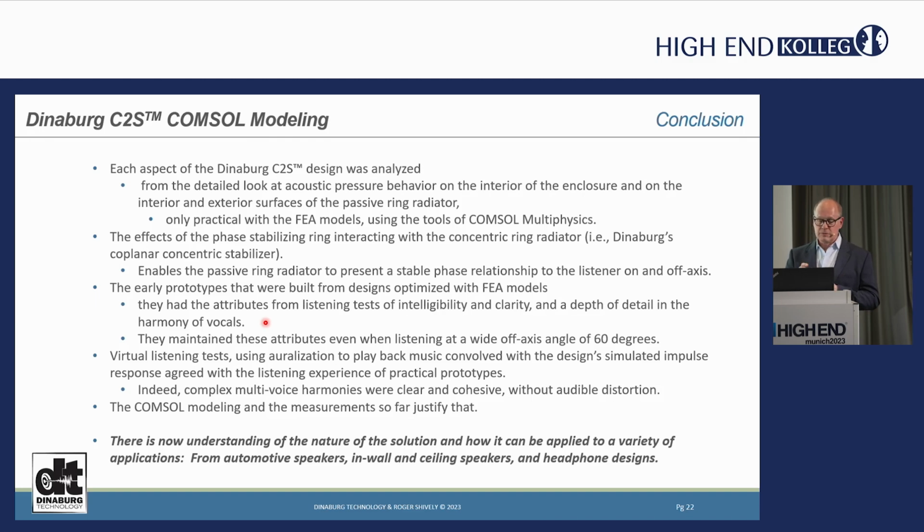But the phase ring, the design ring around the active loudspeaker, has an effect in that it can control the amount of phase between the pressure on both sides of the active and the passive radiator. It can control the phase relationship between the two if we change it. That's not part of what I'm showing here, but there is a study that we have done on that as well, which we can publish.